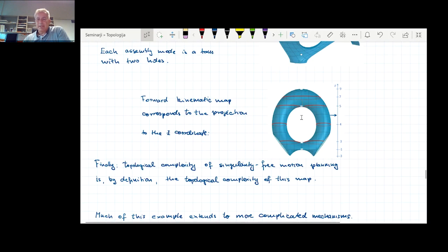And now it says whenever you have something within this space which is not categorical, for example, this circle or this circle, or of course even some bigger subspaces, there must be at least one position here which is a point of discontinuity, a point of instability, if you want to travel to this position in the workspace.